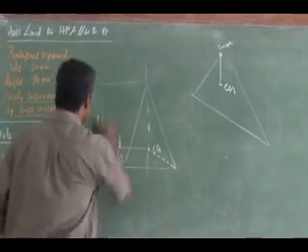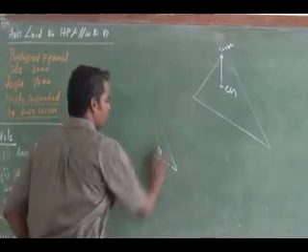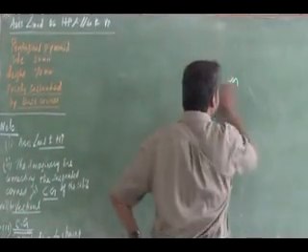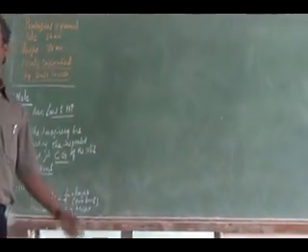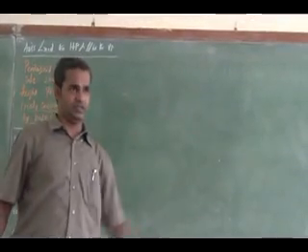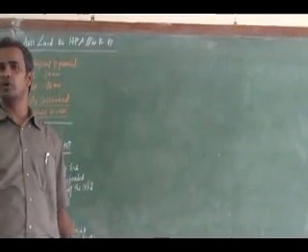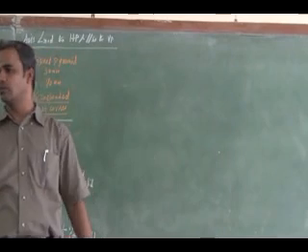So you proceed to start drawing the true shape of the base, the pentagon, on HP. Then you mark the CG in the front view, simple position. Proceed for the tilted orientation, the suspended orientation, then get the final top view.